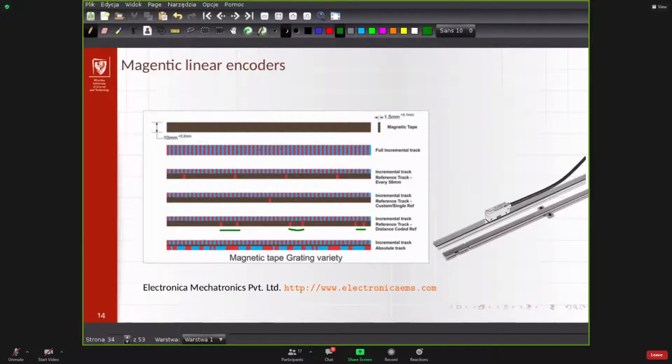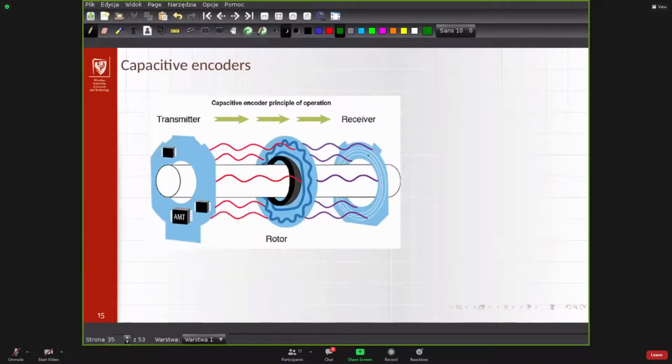Okay, the advantage here is that in fact during the movement the change is continuous. So between the 2 different polarizations, the change is continuous. So in fact you don't have a sharp on-off option as you had in an optical encoder. Here you can also have a bit higher precision resulting from the continuous change of the magnetic field in that point.